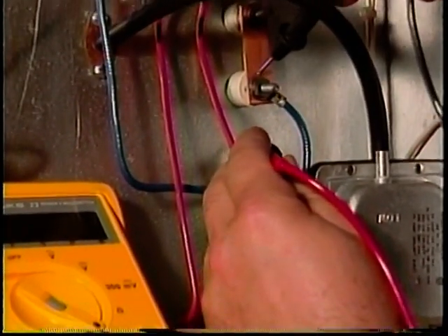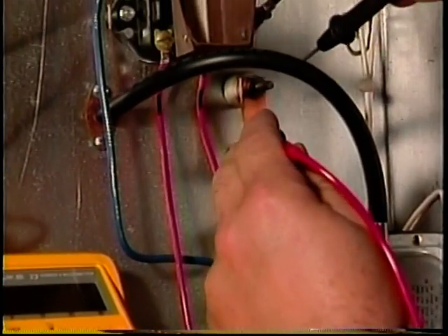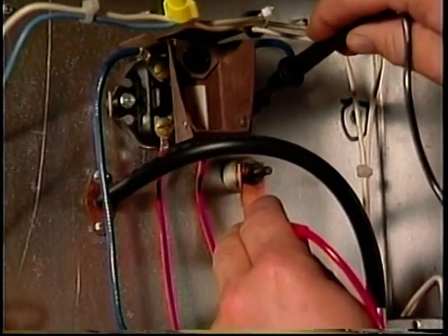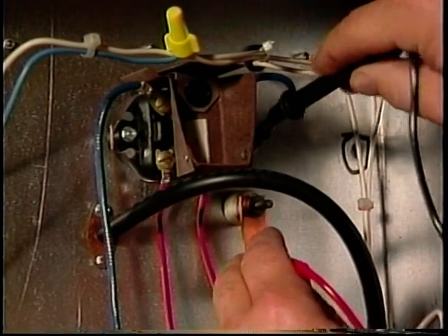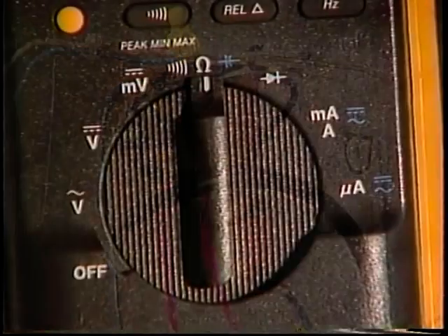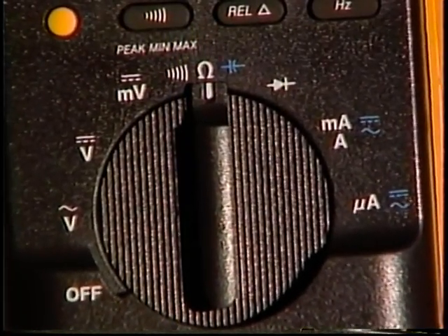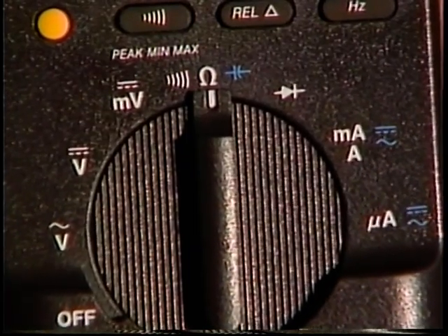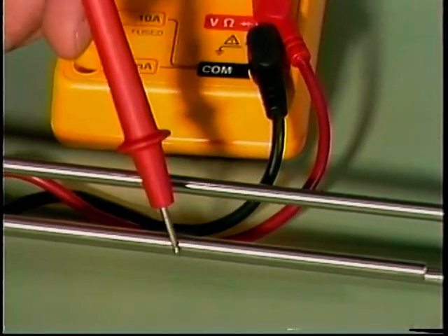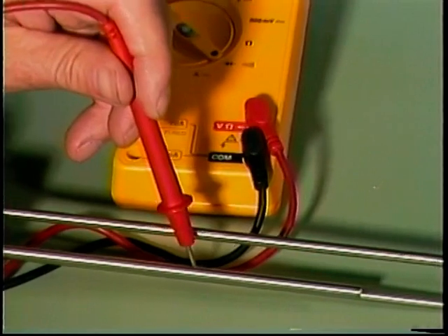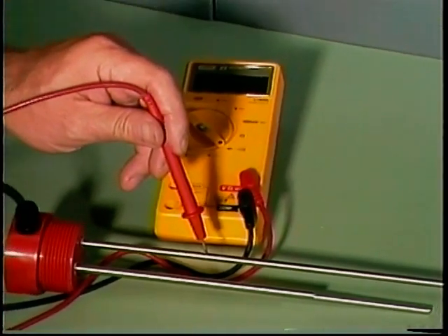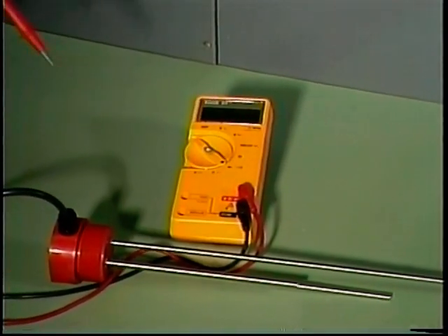To test for continuity, the meter is set to the audio beeper setting. The meter leads will produce a sound when connected together. The continuity setting is commonly used to test removed fuses, switches, contacts, and other components that typically indicate a very high or very low, if any, resistance reading.